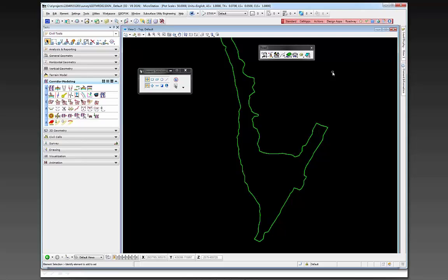You might have an island terrain out there, but all those terrains, if you want to give it to the contractor as a proposed surface, should all be put into one terrain, or at least maybe divided up into corridors, so that all your intersections are all together with your corridor, and so on and so forth. So those have to be built, and the way you've got to build them is from the composite 3D lines that are out there.